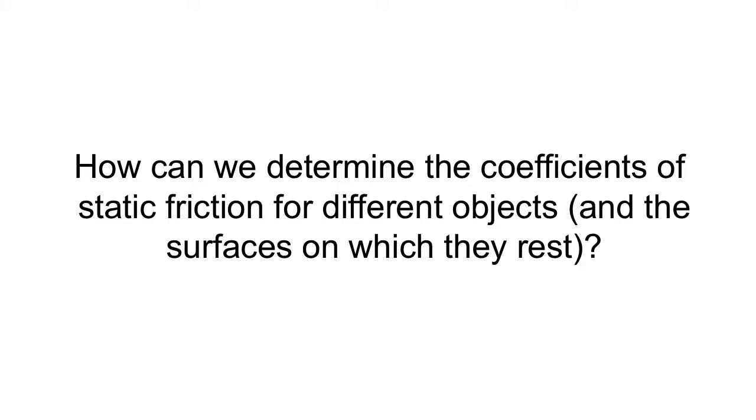So that's pulling us in the positive direction, minus the frictional force, which I have as sub s, the static friction force. Okay, so I just added up all my forces, and I set them equal to 0. In doing that, I get my first expression. I'm just doing some algebra: the static coefficient of friction times the normal force is just equal to the weight times the sine of this angle, theta. Okay? So that's just algebra applied to the system after Newton's laws.